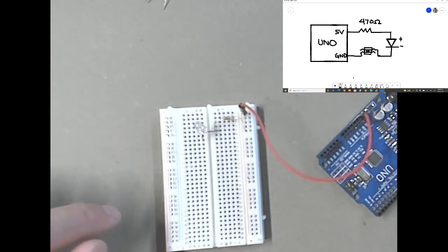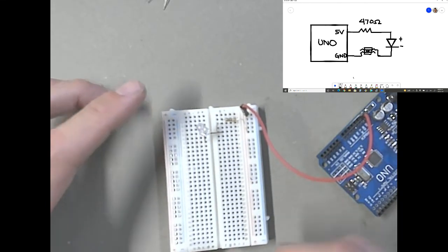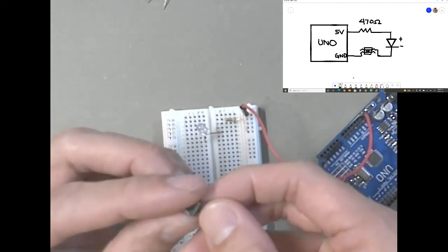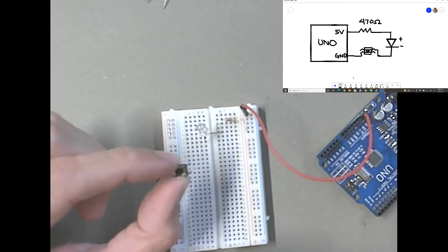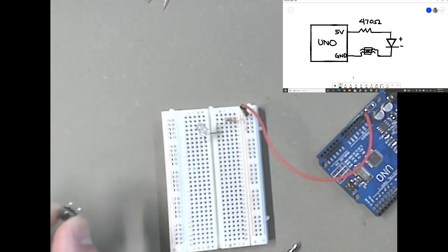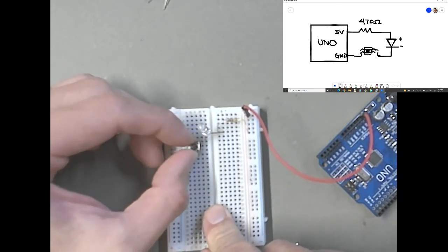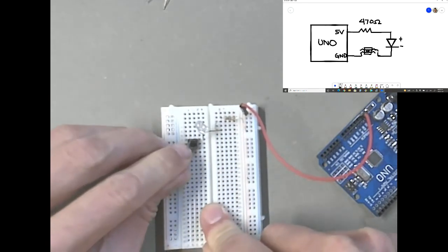All right. So I got my short legs on this row right here. Now what I got to do is take my button, and let's make sure your button is turned the right way, so the legs are on the side. Okay. And on my schematic, I see that the top legs are connected to the minus right here, right? So I take the top legs and put it on the same row as the minus of the light, like that. And you want to stick it in.